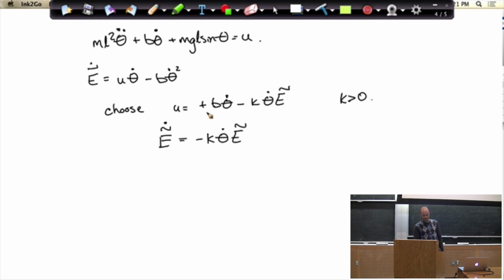Yeah? You use the damping torque. If it's in the right direction, it seems like you could also make use of it. It's true. Which this would sort of do, right? This would fight that and you'd be a little bit better. That's right. Exactly right. Maintain a continuous positive or negative damping, keep taking that into account. So if you're at K minus, you're actually damping, right? It's true. I think this would actually use less energy when the damping is doing the right thing. But you could imagine other cleverness that gets this to be some positive scalar times that always. Exactly.